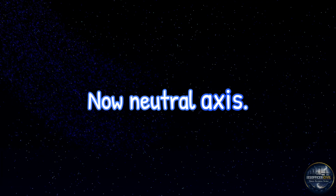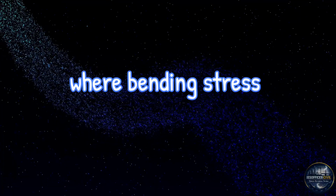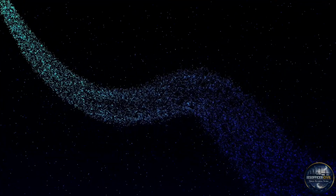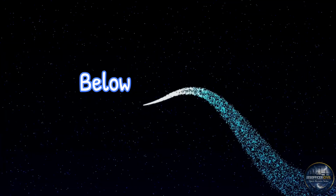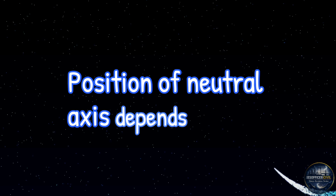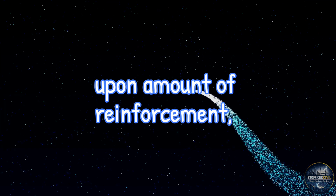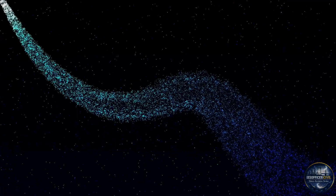Now neutral axis. Neutral axis is the axis where bending stress becomes 0. Above neutral axis, compression develops. Below neutral axis, tension develops. Position of neutral axis depends upon amount of reinforcement, modular ratio, and beam dimensions.